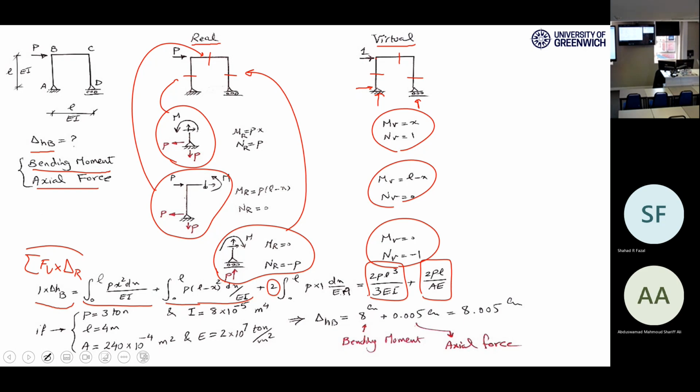That's why in majority of cases, the designer of the tutorial or example says, just eliminate the contribution of axial force or shear forces. Because in majority of cases, it's like this. The contribution of axial force into the deformation is negligible. Axial force is there, it is not zero. You cannot neglect axial force. Axial force is there, it should be there to satisfy the equilibrium equation. But the contribution of axial force into the deformation is negligible. Right?